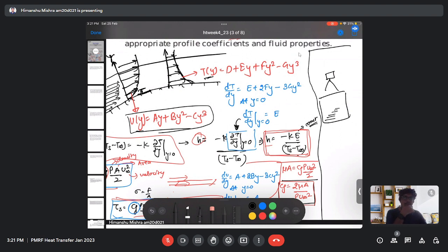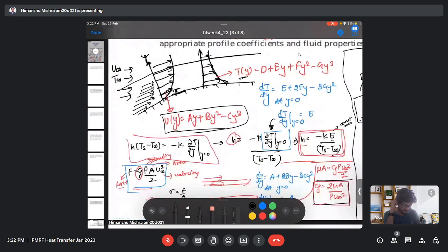That force we can categorize as a drag force, because since there is a rubbing action, there is a transfer of momentum between those molecules, because one molecule is transferring its momentum to the other molecule, and due to the net change of that momentum, there will be a force, and that force will be the skin drag force that we have just defined here.